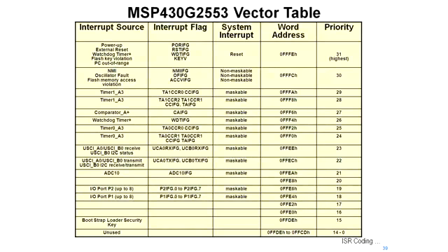The power up, the external reset, the watchdog timer, a flash violation, the PC out of range will all generate a system reset interrupt. That is at 31, the very highest priority on the device. Just below that is the non-maskable interrupt. That could also be oscillator faults, flash memory access violations would all generate a non-maskable interrupt. Of course, the reset and the NMI are the only non-maskable interrupts in the system. You don't want to be able to mask those out, and they're both the highest priority.